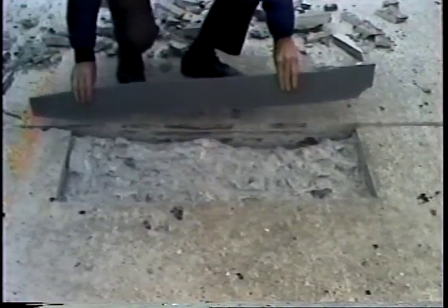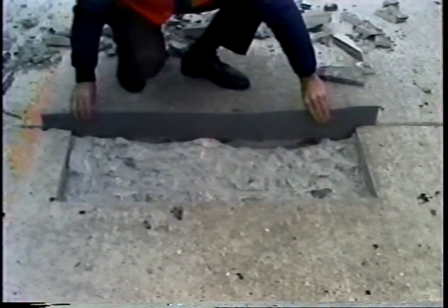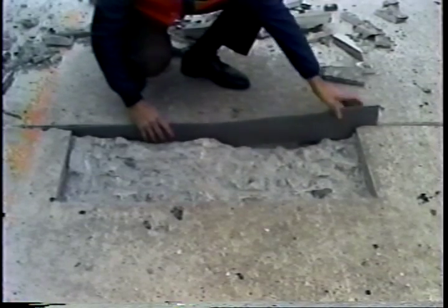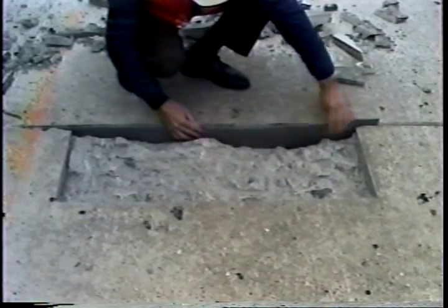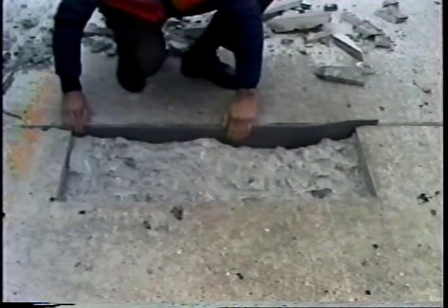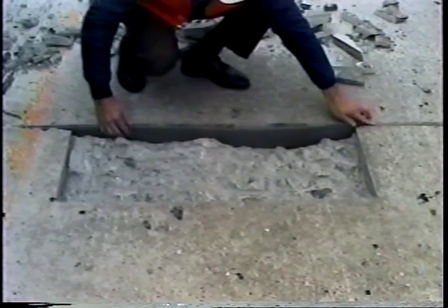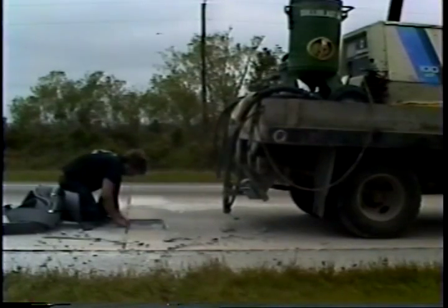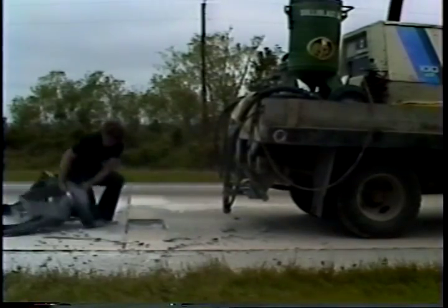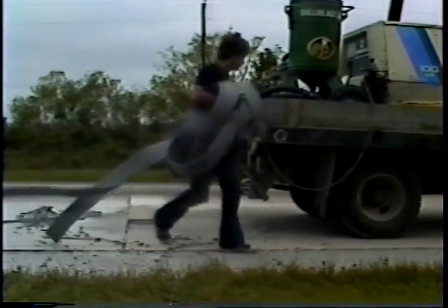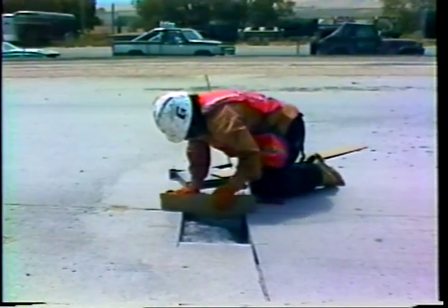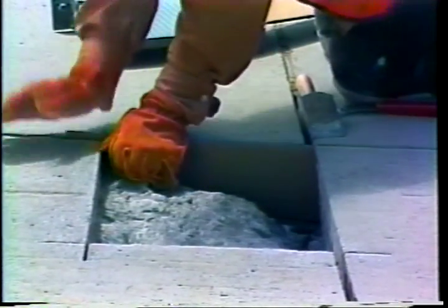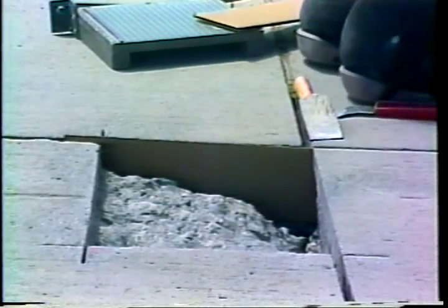or eliminated. At transverse joints and cracks, the insert has to extend an inch below the bottom of the repair area, and laterally 3 inches beyond the end of the repair area. Sawing may be necessary to obtain these dimensions. Polyethylene, styrofoam, and asphalt-impregnated fiberboard are all acceptable inserts. These same materials may be used at longitudinal joints and cracks. When extra side support is desired, stiff polyethylene strips or a thin piece of plywood may be used.